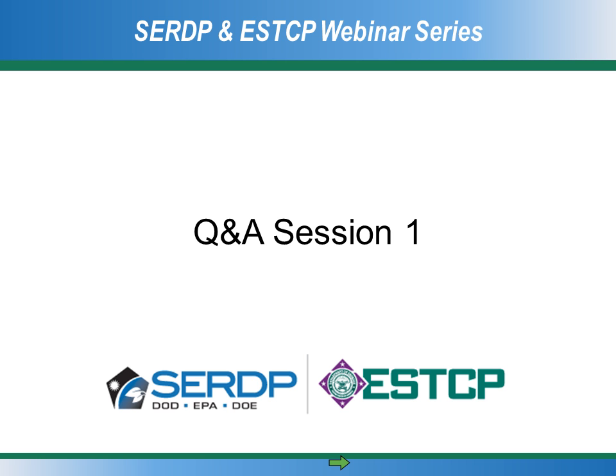And then saturation, it doesn't tell you the saturation. We determined that because we had nearly co-located soil samples and could correlate the response to the saturation. The last part of that question is, does it provide insights on the nature or the type of contamination? And yes, it does. We found from our laboratory testing that different types of DNAPLs responded differently to dyes, and then we could select different dyes to target and identify different types of chlorinated solvents.